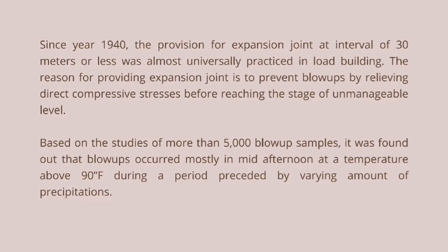Based on the studies of more than 5,000 blow-up samples, it was found that blow-ups occurred mostly in mid-afternoon at a temperature above 90 Fahrenheit during a period preceded by varying amounts of precipitation.